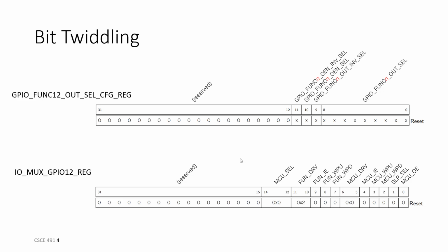Make sense? Because otherwise, if you get the wrong address, it just won't work, and then you run the code and it's just bricked, and you're like, well, what's going on? What do I do? Do I run the debugger? No, there's no debugger. So what do you do? And this, as you can tell, happened to me a lot, right? Partly because of this: the addresses to these are not given to you. All you're given is the base address for the first func, and then you have to do math to figure out what the 12 func register is, right? You do that math wrong, and then you write to it, and the system just ignores you and doesn't give you any kind of error return or exception or anything like that. It just doesn't work, okay?